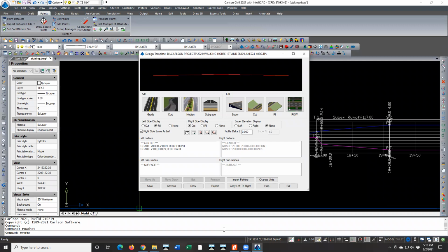So let's get you a solution. That's what we need to do here. All right, so if we look at this now, I'm going to go ahead and request remote control just in case I need it for anything. I don't know that I will. You still have control, but I just want to take a look at this. So I'm going 20 feet out at that slope, calling it my ditch front. And then I'm going flat for 2 feet at the back of the ditch.